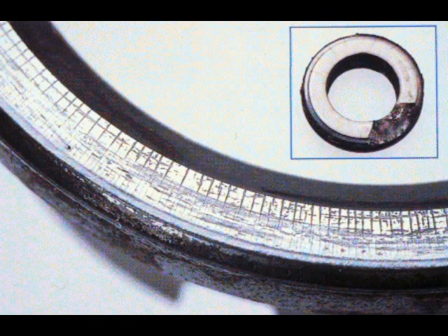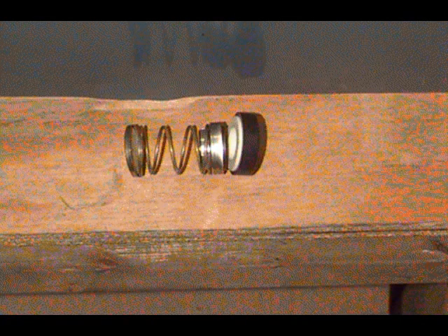This will result in thermal cracks on the face of the seal. Abrasive damage can cause mechanical seal failure. When small abrasive particles work their way between the seal faces, they may groove the mirror finish of the faces, or they can leave deposits from evaporation of the liquid. When these deposits build up on the shaft, they will freeze the sealing elements to the shaft and eliminate all shaft flexibility. This condition can be especially severe when Teflon sealing wedges are incorporated in the seal.